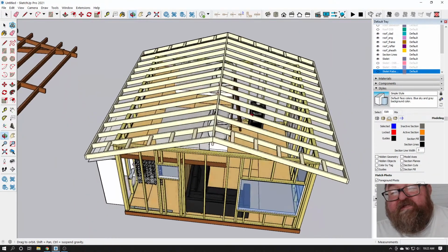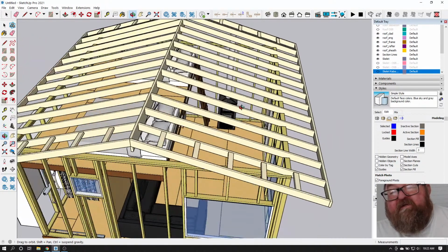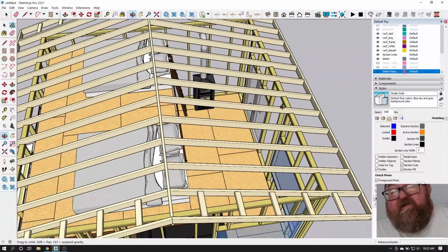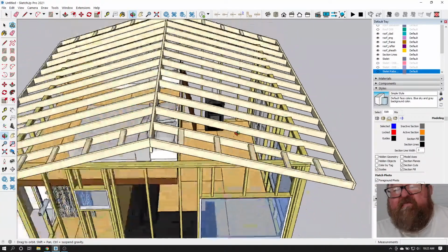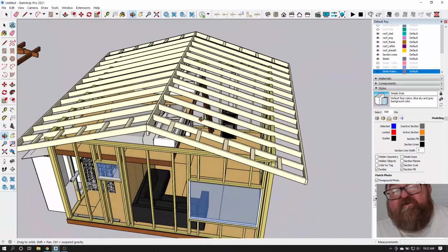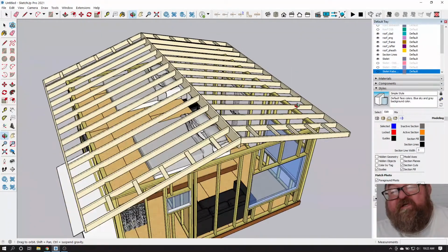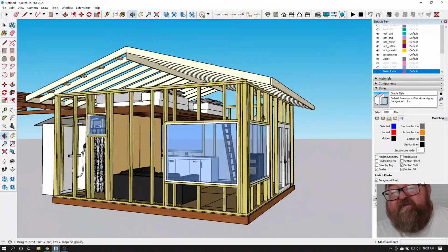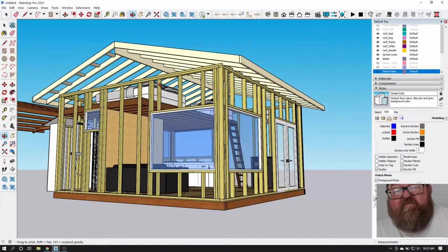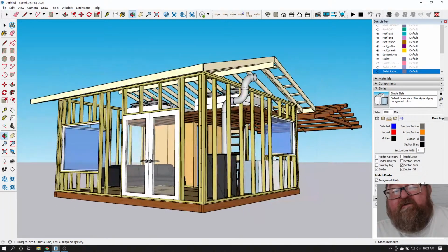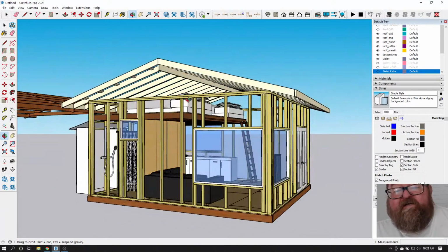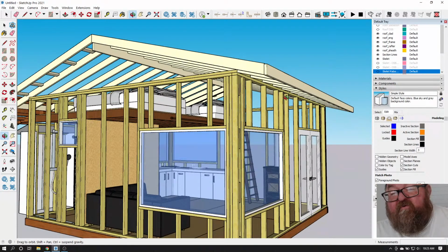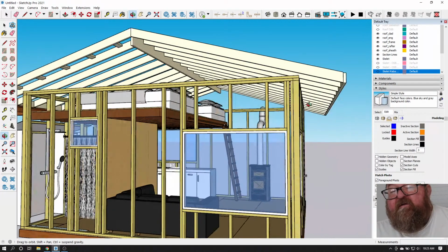And I have literally seen this before, on big buildings. I've had to take chains and come-alongs and pull walls back in because somebody didn't have proper structure, and the rafters were pushing the walls out. They will literally lean out, especially in the middle. These walls on the ends are holding the corners. This wall is acting as a collar tie for the corner, but down here in the middle, this wall will literally push out.